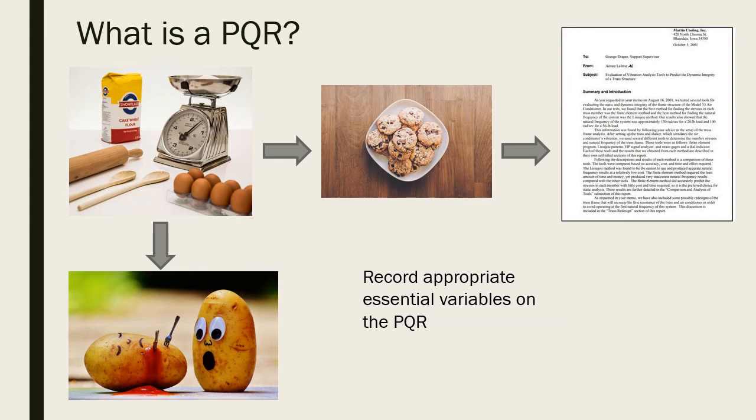But all joking aside, a PQR is just a document that documents our science experiment, what we did, what kind of metal we used, what kind of filler metal we used, if you're welding it to a code that requires positions. AWS D1.1, they want to know what position you're going to weld it in. ASME Section IX doesn't care.